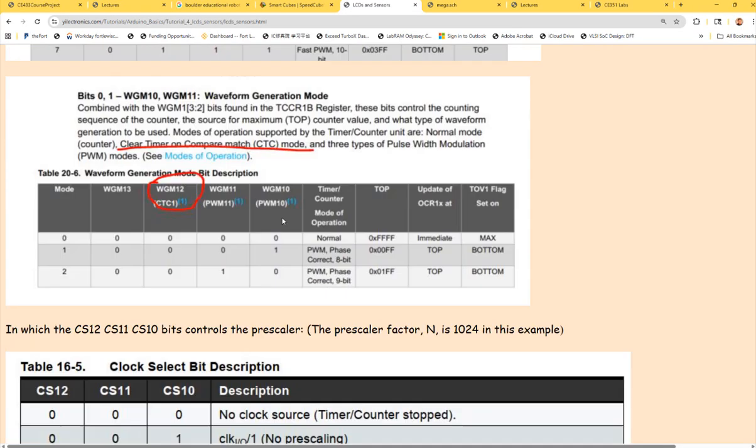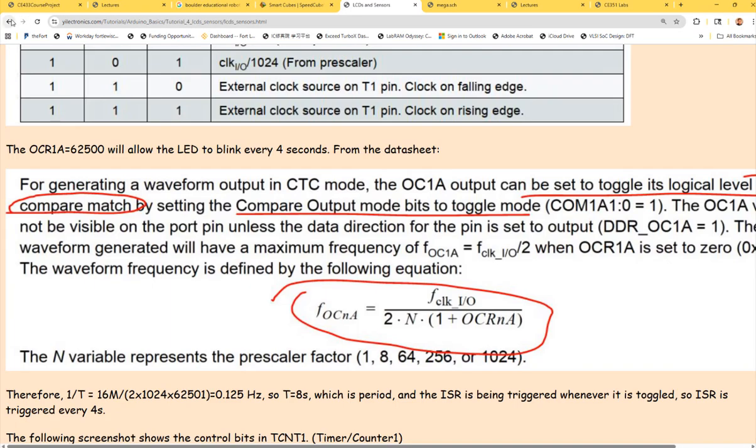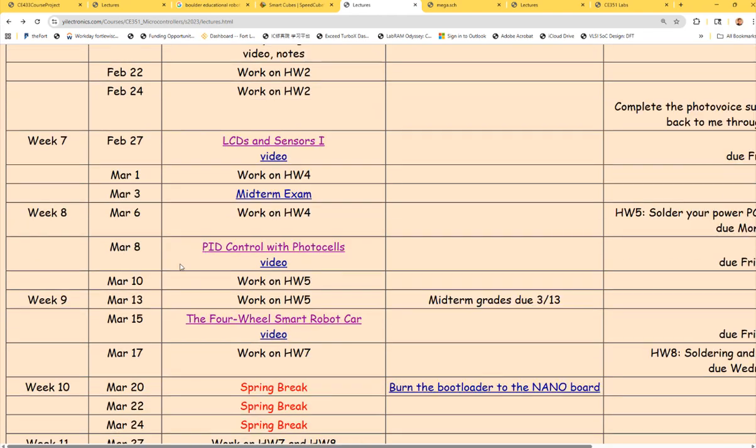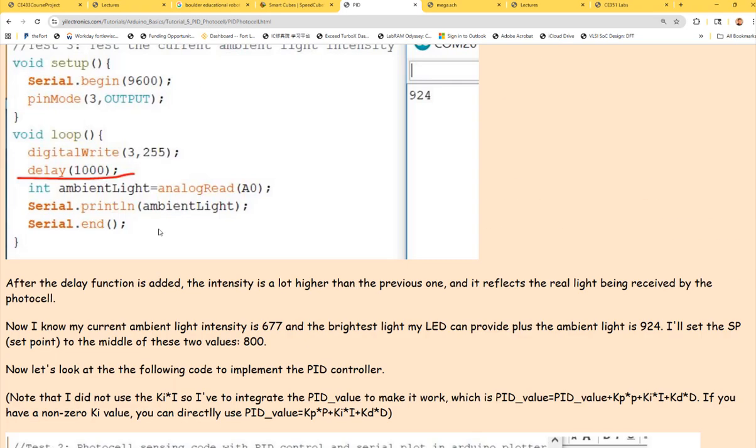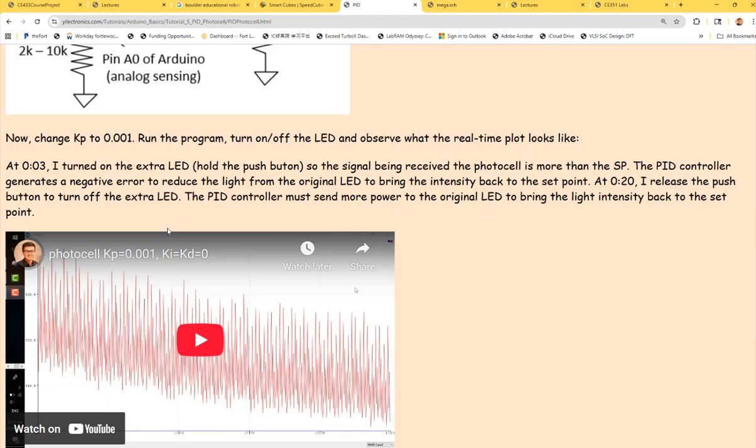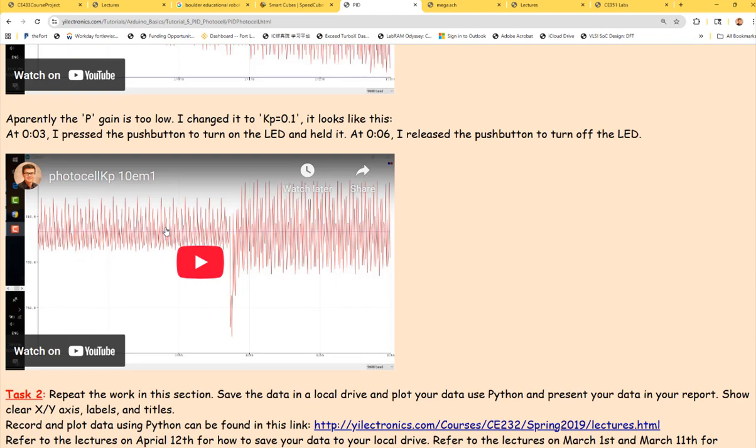And okay, this is this one. And also I have this, called an LDR, a light dependent resistor. Depending on the intensity of the light, it changes the resistance, right? So you can measure the resistance output and convert it to the light intensity. So this is a light sensor. This can be used for light control in the room, right? All these kinds of things.